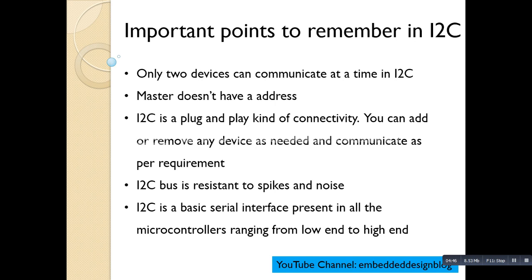And even though the other masters on the bus hear it, there is no use because they have not shared any data, so they will just ignore whatever commands are coming. So now we can say when a slave replies back or a master communicates, it's a universal communication. The master sends it over the bus, all the slaves will receive, and only the respective slave will respond if the address matches. And one more important thing with respect to I2C is that I2C is just a two-wire communication with just two pull-ups from the hardware perspective.